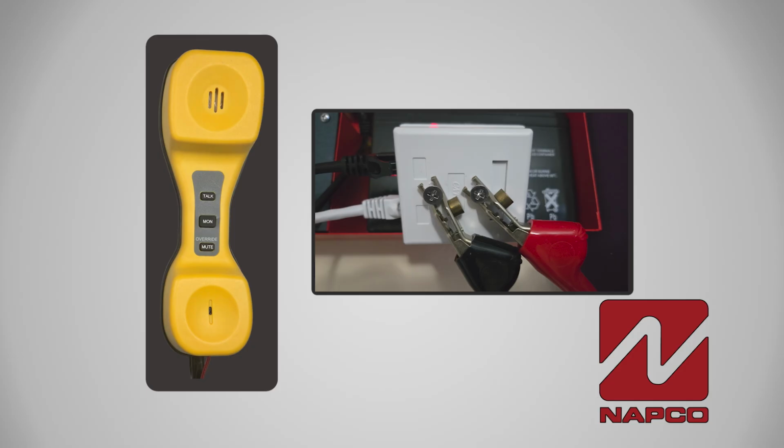This is most easily done by disconnecting the NAC circuit on the panel, which has the effect of both transmitting a trouble within 30 seconds and it prevents you from making a lot of noise in the building. Finally, listen for the transmission from the alarm panel. Now that we have covered the troubleshooting steps, let's discuss what could go wrong and what the solutions are.